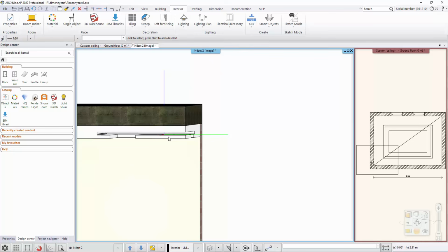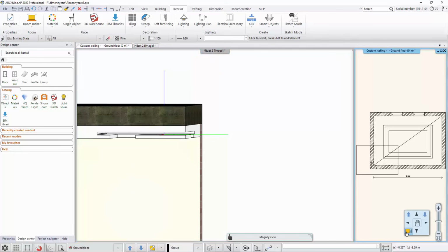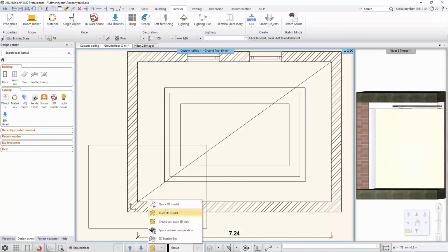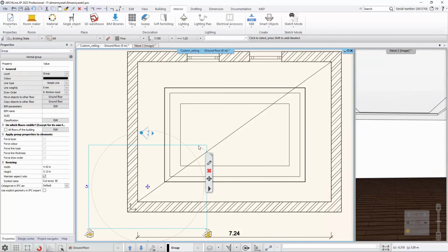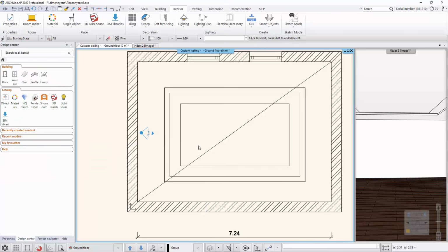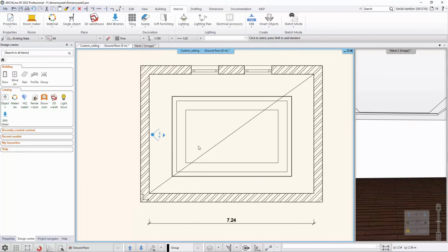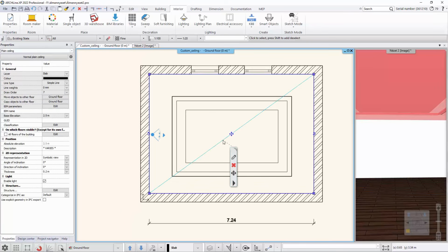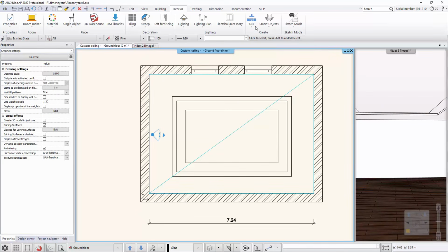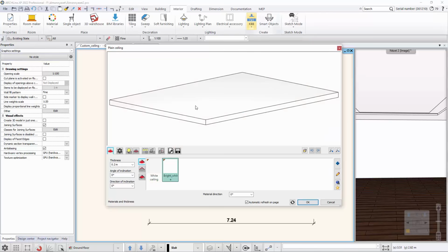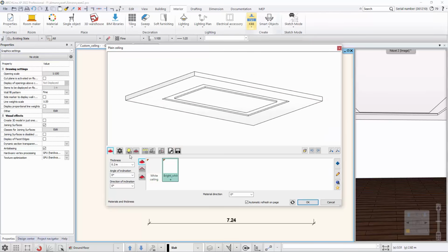Now we go back to the floor plan, rebuilding the 3D view. I delete the partial construction drawing. In the next step, spotlights are recessed into the ceiling. Spotlights will be part of the ceiling. Therefore, we add spotlights to the ceiling under the Modification tab.